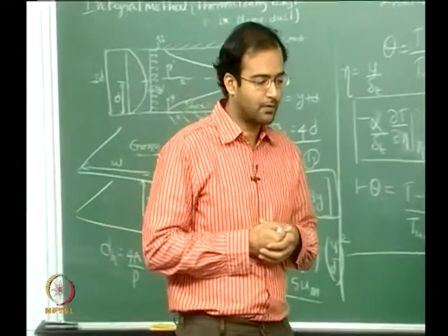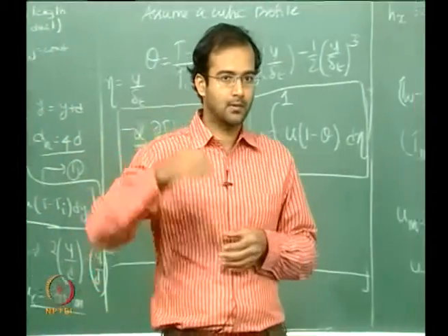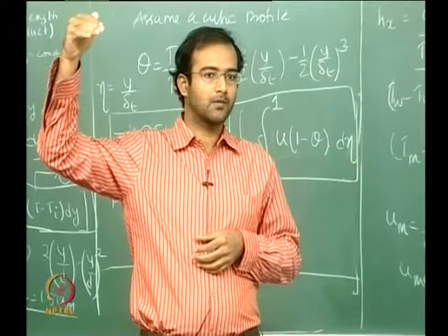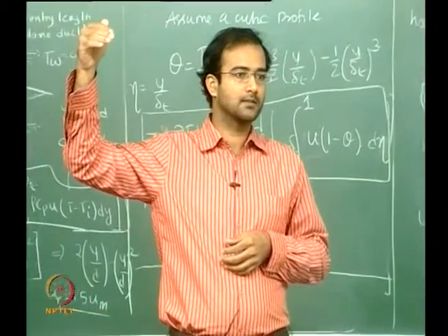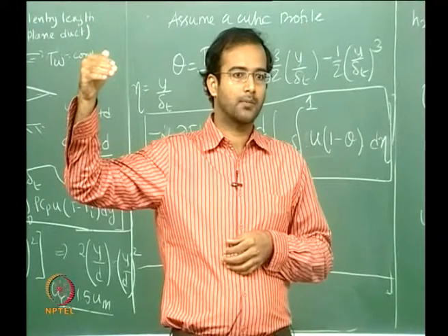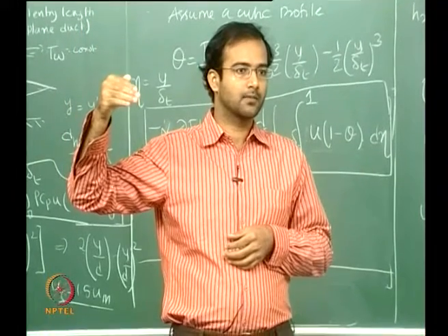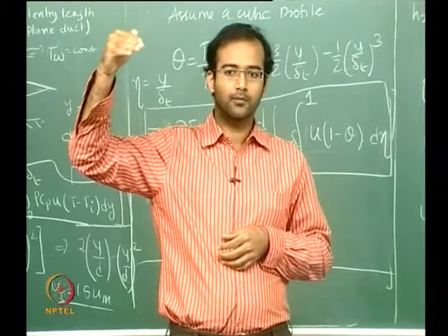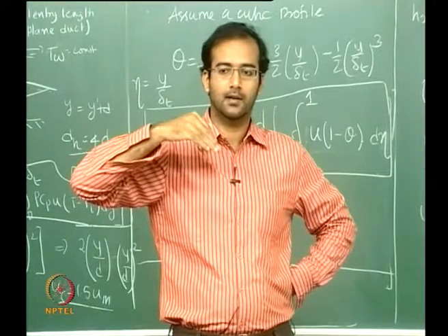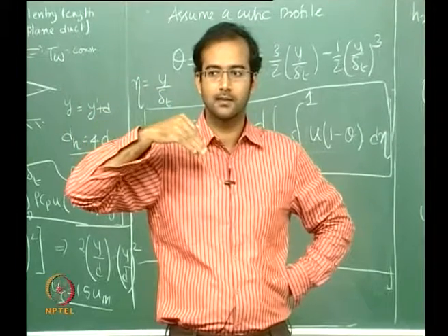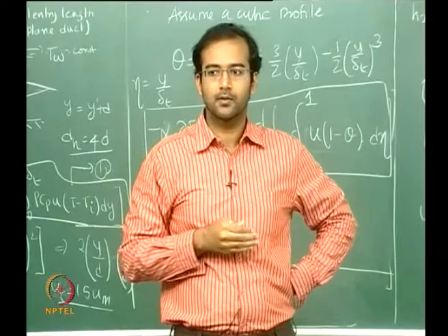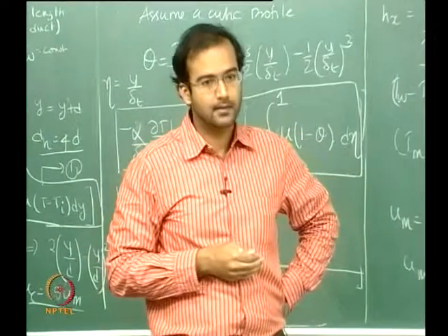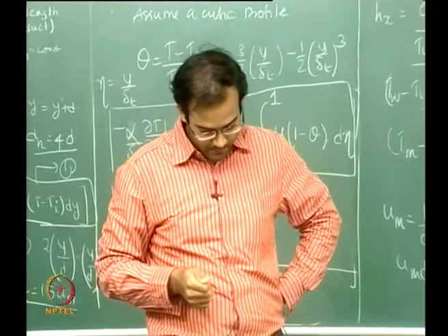And the order of decreasing Nusselt number starts from your channel flow. The highest value comes for the plug flow case with the constant wall flux, then constant wall temperature, then your parabolic velocity flow. So it goes in that order, starting from 2D duct flow, then 3D circular ducts, and then finally your triangular cross section. This is the hierarchy in which the Nusselt number decreases.